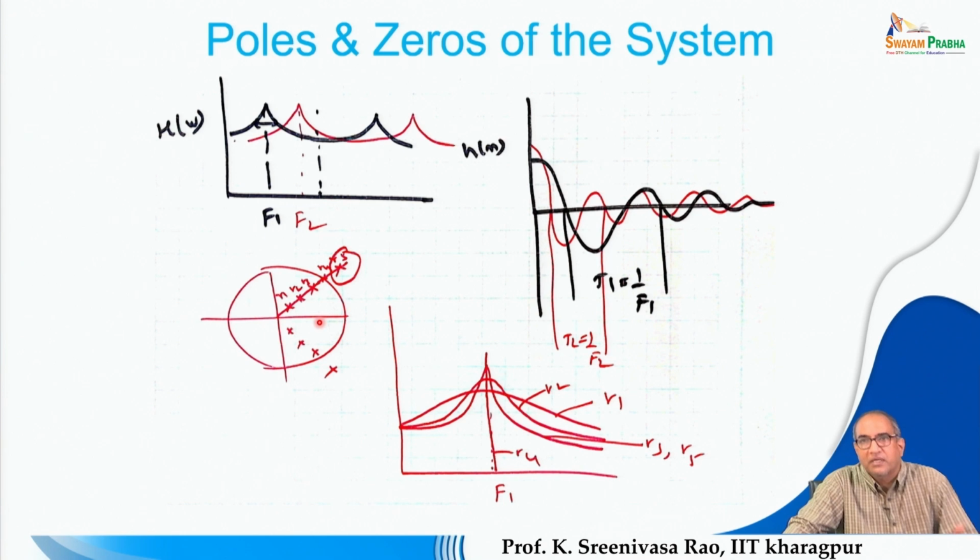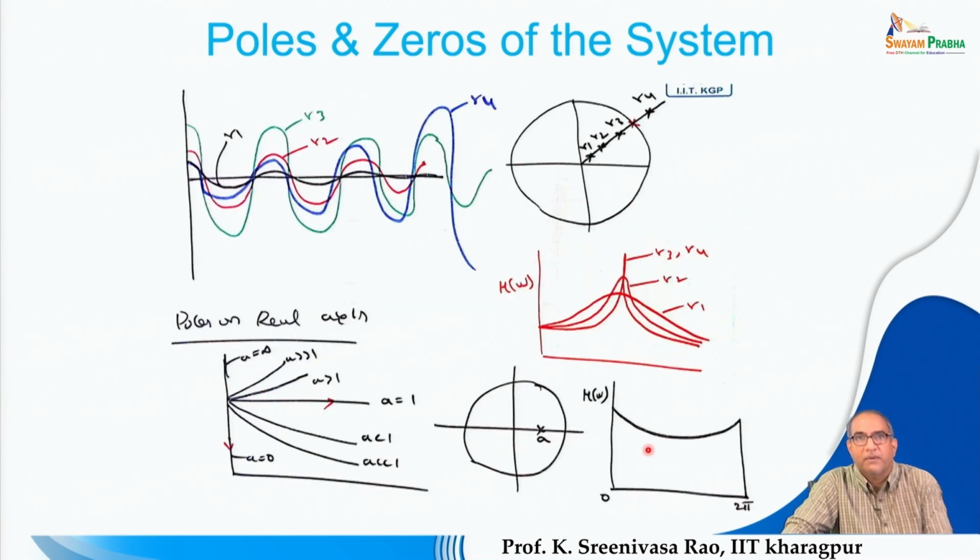So, the same concepts apply here in the discrete domain, where we use the Z transform and make use of poles and zeros, and with the poles and zeros you can carry out the analysis and state whether the system is stable or not. And here you can see that there are two things. One is the angle posed by the complex conjugates, and the second is the radial distance. The angle indicates the frequency of oscillation, and the radial distance indicates the sharpness or bandwidth, and also the damping nature of the sinusoids.